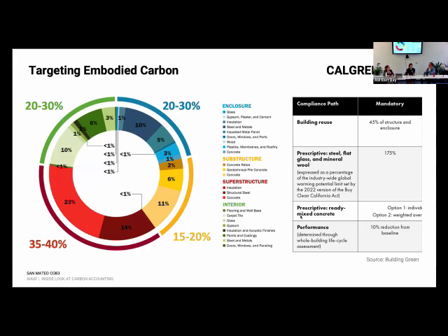I would also say that EC3 isn't the end-all, be-all for embodied carbon for everything, but it is a good starting point. I believe there's a Buy Clean California compliance filter on there, which will tell you at a glance which manufacturers fall below that. The only thing I would caution you on is that there's an uncertainty factor built into the numbers on EC3, so it might not be the exact number that shows up on the facility-specific part of the EPD. So just make sure you're double checking that.